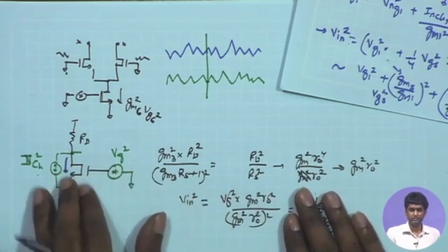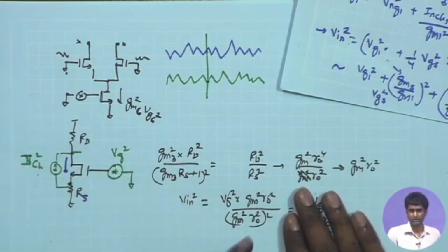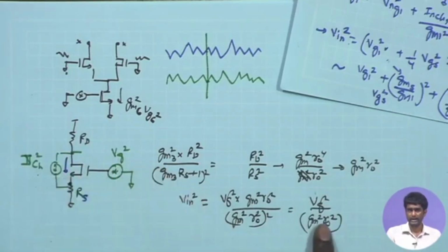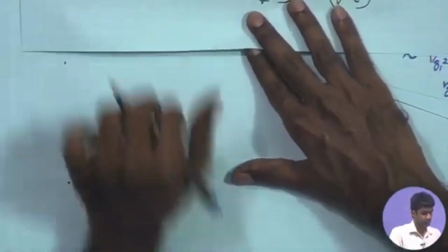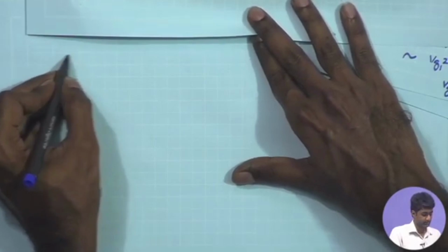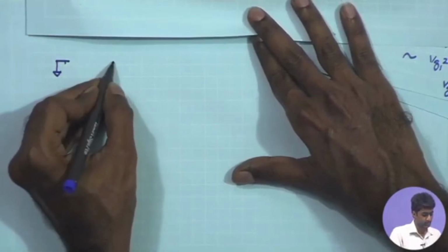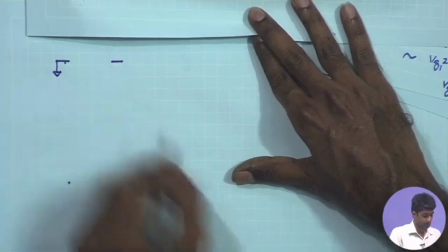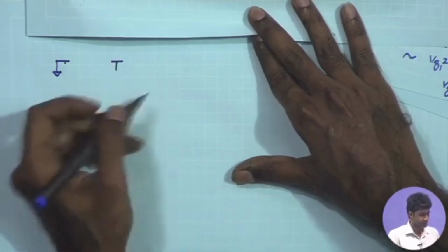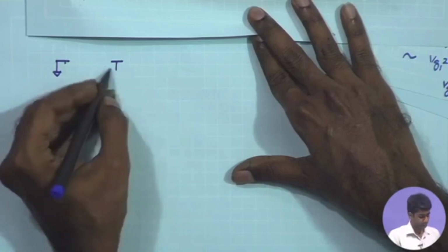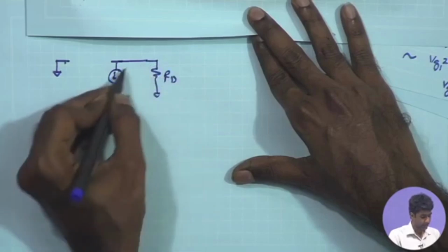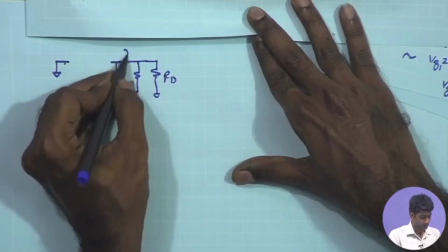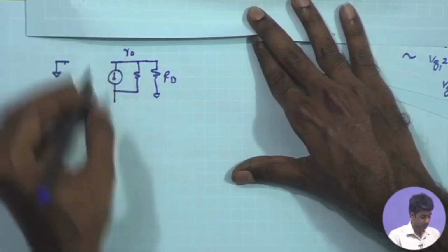And analytically also, in this circuit, we can try to solve the KCL and figure out what the expression for I channel is. We can do that very quickly. If I look at this model, assume VG is 0. So the MOSFET gate is 0. Gate potential is AC ground, and I can look at the GM VGS term. You have the RD, which is between the drain and AC ground, and you have the RO, and also you have the RS over here.